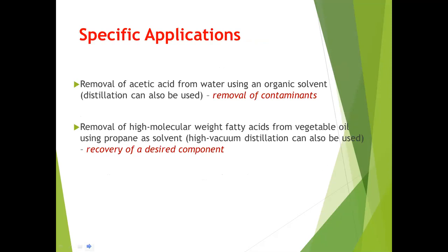Now, as to specific applications, sometimes liquid-liquid extraction is used as an alternative to distillation. Although, sometimes distillation is highly favored over it because extraction uses a solvent. If it uses a solvent, there is a need for the solvent to be separated from the component that it extracted from the feed.